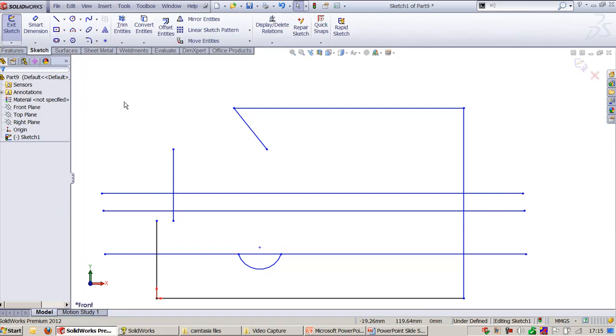And with the continuation of this, I would like to show you the interesting extend entities tool, which will help you to exactly extend. If you have the boundaries, definitely the entities will be exactly extended. This I have to extend, and this I have to extend, and here I want to extend. So extending an entity is easy.